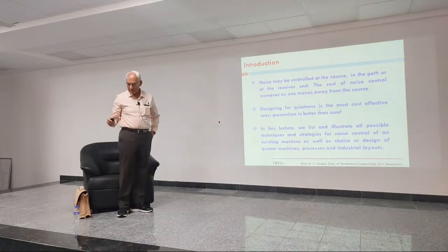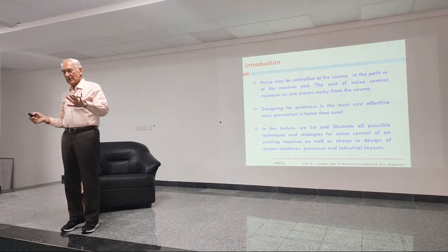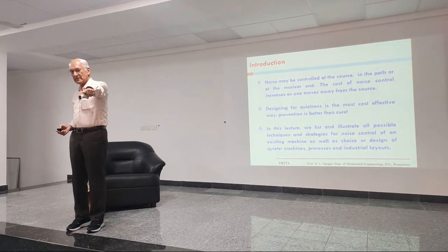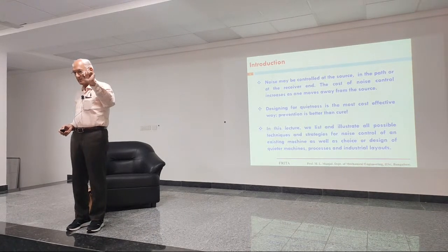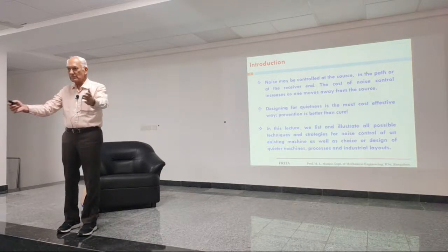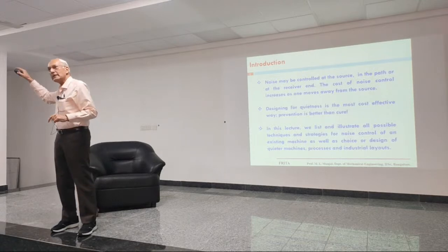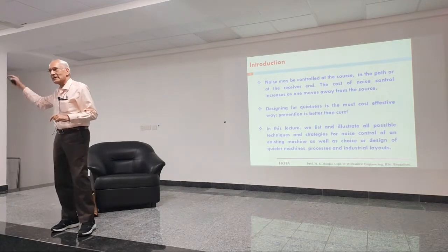So please try to always understand that in any new situation, you have to ask: noise is coming from there, so can I do something right there? And finally, if someone is getting disturbed there, can I do something on the way, or in the path? If I cannot do that, can I finally help that person with hearing protection?